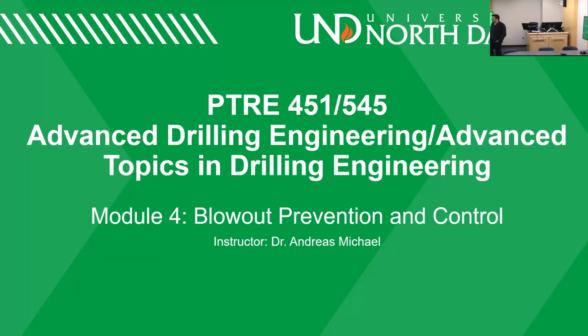What do you expect the density of the kick to be with respect to 9.6? More than 9.6 or less than 9.6? Should be less. Why do you expect it to be less? Because the shut-in casing pressure is more. It's more than the shut-in drill pipe pressure. Okay, that's a good guess.